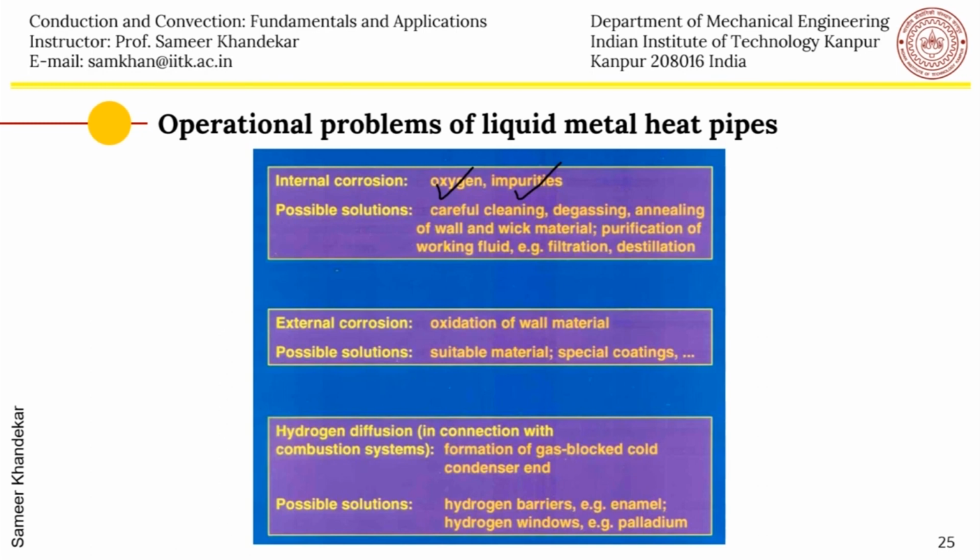Then one can also make large heat exchangers, for let's say thermal energy recovery. So hot air can flow in half of the heat pipe, and these heat pipes can then transport this heat from the hot exhaust gases to the incoming gases for boiler operation or for some other industrial use.